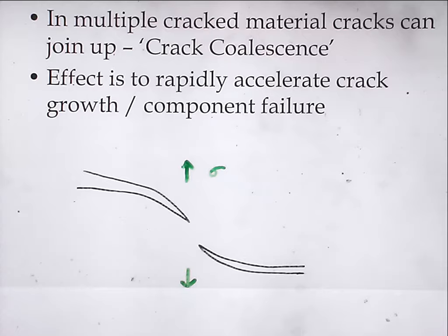That's intergranular. It does exactly what it says on the tin. The cracks are growing down the grain boundaries, and you can actually see individual grains on the surface, which you could probably see on that stainless steel specimen that was going around if you looked at it carefully.